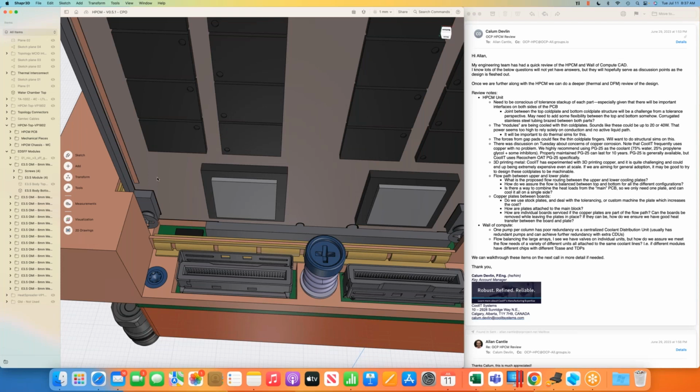So okay, yes, exactly. In fact, when I was talking to Micron, their CXL.mem is a double width module, and so is Samsung's with air fins, because they do burn about 40 watts, which needs double width. But we want to stay roughly in the single width, and so we did take the lid off, and sure enough, the components seem to be within the tolerances of a single width card. It's just double width because of the air cooled heatsink fins.